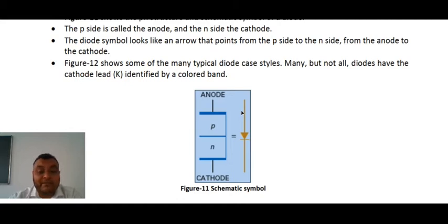Okay, so in practice when a figure is given, on a diode you can see there is one line drawn over there with silver color, so that part is known as cathode. और वो क्यों देते हैं कि जब सर्किट में आप कनेक्ट करते हैं डायोड को तो आपको इजीली पता चले कि भाई एनोड की साइड कौन सी है और कैथोड की साइड कौन सी है. सो बाय मिस्टेक आप उसको गलत तरीके से कनेक्ट ना करें प्रैक्टिकल करते वक्त. ओके, so this is the symbol of diode. Okay, so please remember that, and it is formed with the formation of that PN junction material.